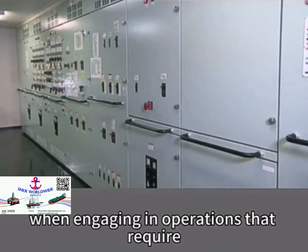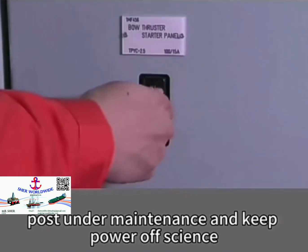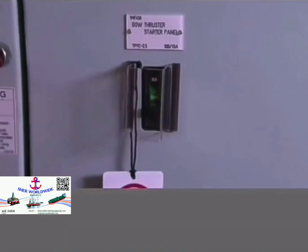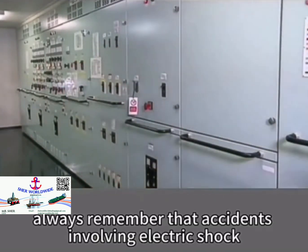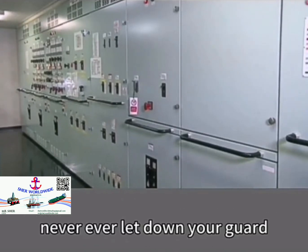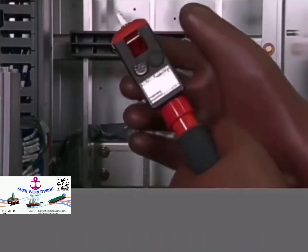When engaging in operations that require power to be shut down, post "under maintenance" and "keep power off" signs so that power is not mistakenly switched on. Always remember that accidents involving electric shock are prone to occur immediately before work is completed. Never ever let down your guard until you leave the danger area, even if your work is finished.